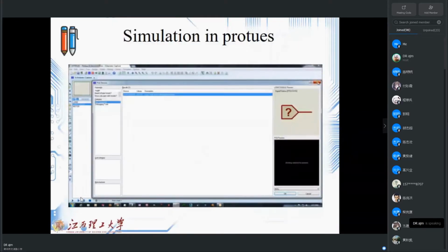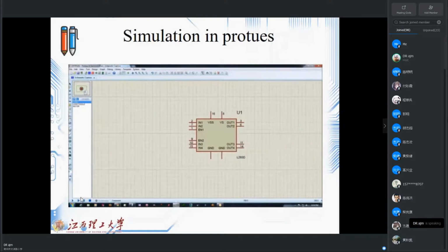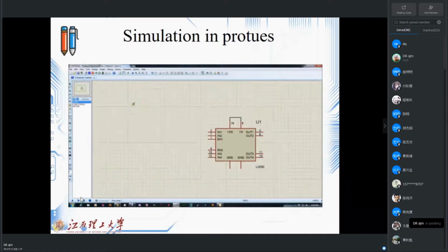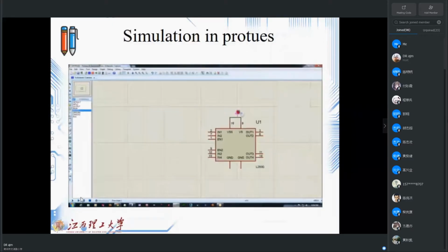Now let's start. First we'll put the driver, then I need the motors. I select the motor and connect it to OUT 1 and 2. Meanwhile, it's better that I connect the VCC voltage together, meaning pins 6 and 40 generally, which will be 5 or 12 volts. I will put a label here to make it better. And this ground also should be connected together. After connecting them, I'm going to connect the ground like this.